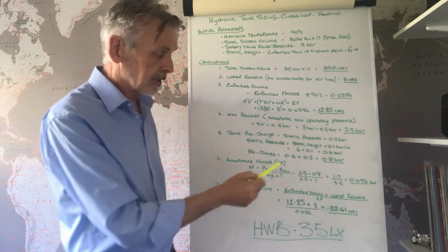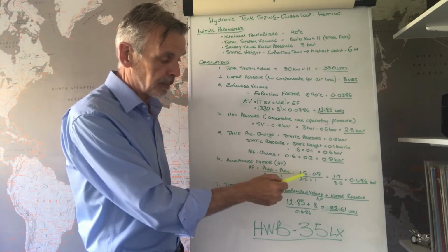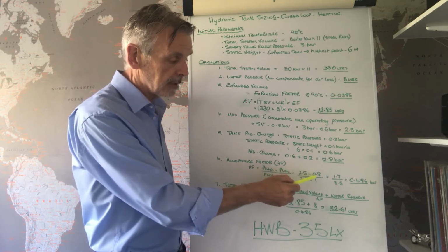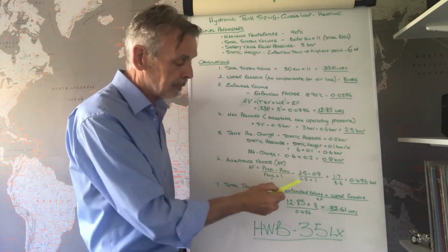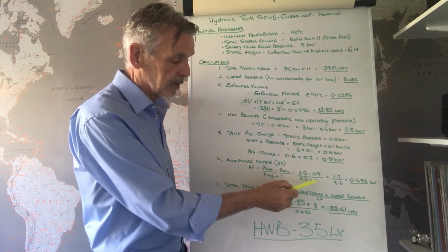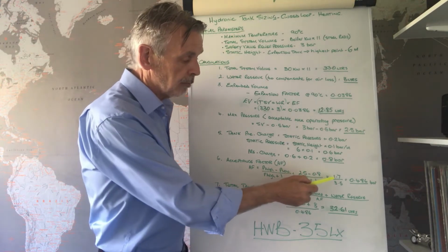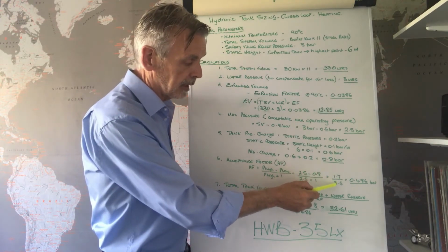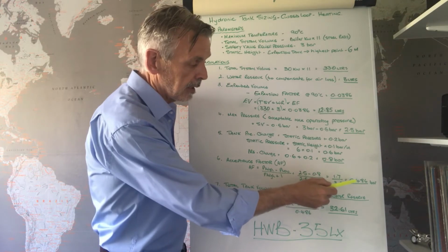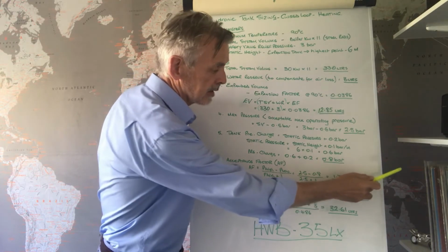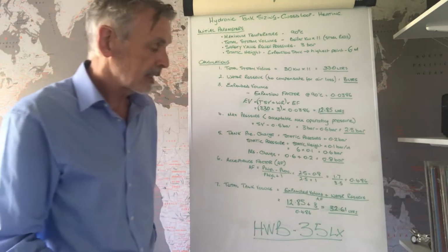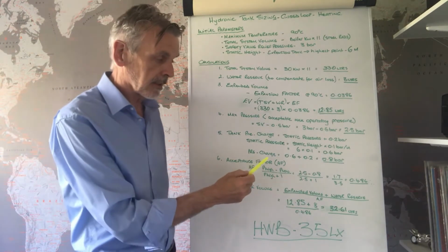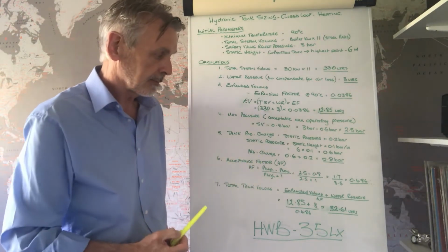So in this calculation, the high pressure that we've calculated is 2.5 bar minus 0.8 bar, divided by 2.5 bar plus 1 bar atmosphere, which is 1.7 bar divided by 3.5 bar, which is 0.486. That's an acceptance factor.